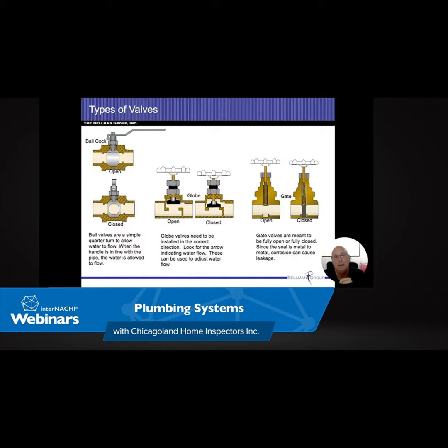Typically, you find this happening in vacant homes. Sometimes people think that it's because the water that was in there evaporated. It may be. It's hard to tell. But if the water in the trap evaporates, you can tell them to go ahead and put vegetable oil or some sort of oil in there, which tends not to evaporate as fast as the water does. But if there's hair in there and that hair is pulling it up, that'll actually siphon out faster.